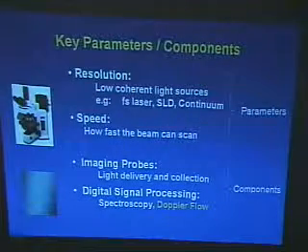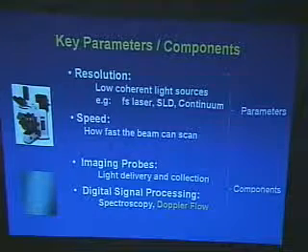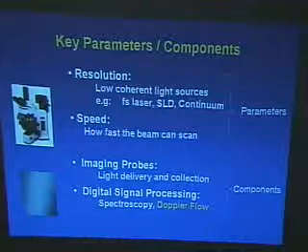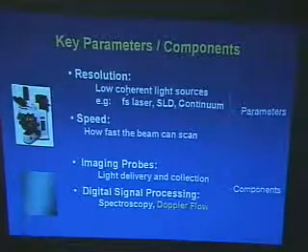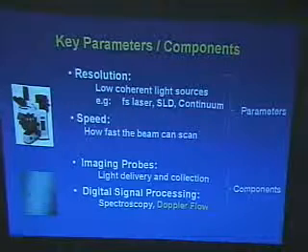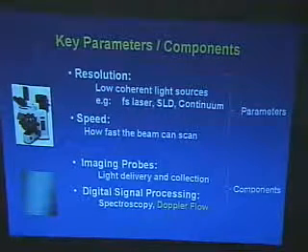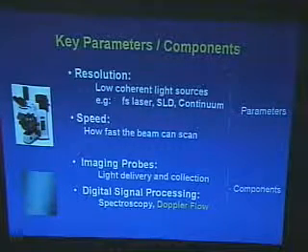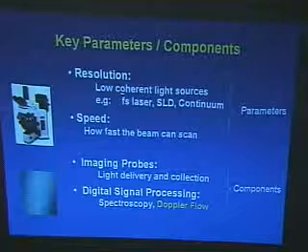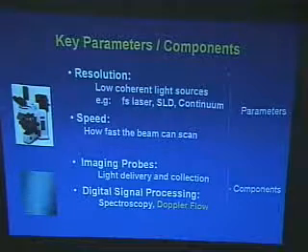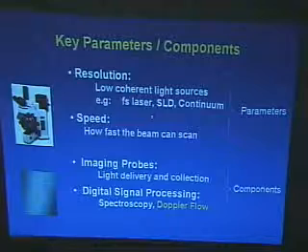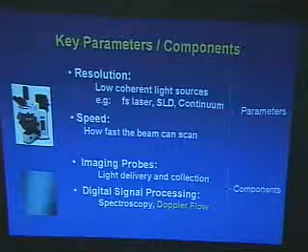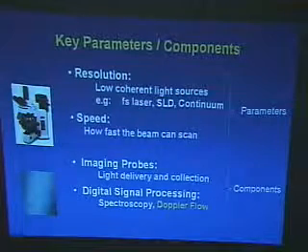So here are just some key parameters. For any imaging technology, we ask ourselves, what is the resolution? How are you going to improve your resolution? What determines the resolution? In this case, the resolution is very interesting. For OCT, the axial resolution is determined by the light source. I'm going to talk about that a little more in a few seconds. The light sources we can use for this kind of technology include femtosecond lasers, really short pulse, SLD, superluminescent diode, which is a different version of an LED, and continuum generation using nonlinear optical processes, which we will not talk about in detail.